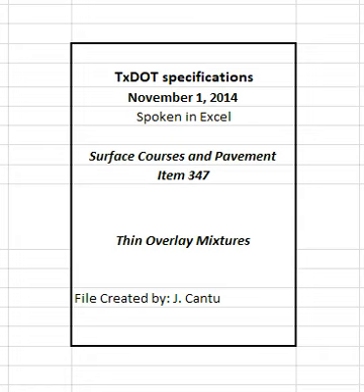4.4.2.2.7 Approval of JMF2. The engineer will approve JMF2 within one working day if the gradation meets the master grading limits shown in Table 6 and is within the operational tolerances of JMF1 listed in Table 8. The asphalt binder content established for JMF2 is not required to be within any tolerance of the optimum asphalt binder content established for JMF1, however, mixture produced using JMF2 must meet the VMA requirements shown in Table 6.